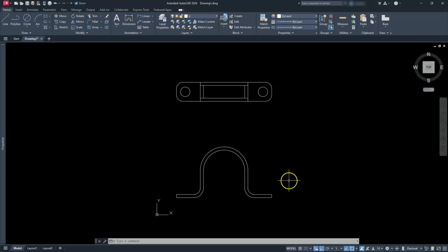The way a miter line works is that I have to create a 45-degree line from basically this corner where these 2 parts meet, and then I can track these lines off of it as well as this line to create my shape that's located here. So the first thing I need to do is create the miter line. I'm going to use a construction line. I'm going to choose angle. I'm going to type in 45, go ahead and hit enter.